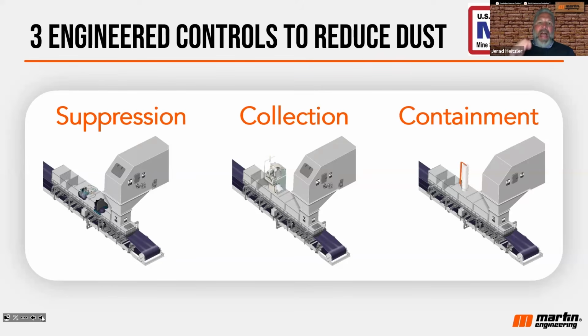Performance components. Go back to the basics here. This is Conveyors 101, gang. Make sure that you fully look at all those performance components when you have dust problems. Performance components, sealing systems, dust curtains, slowing that airflow down. Don't add water to your process. If you do, you're going to have those unintended consequences that you're not aware of quite yet. You're going to cause material to stick to screens. If you add water, material is going to stick to the side of hoppers, and you're going to have to react to those problems. Focus in on those performance components that we talked about earlier.